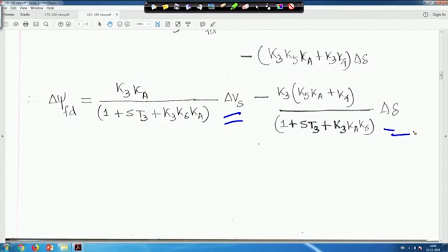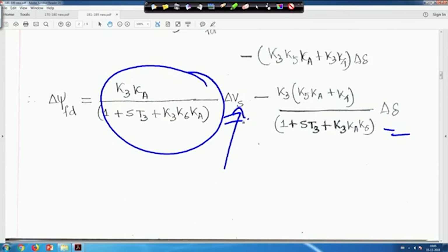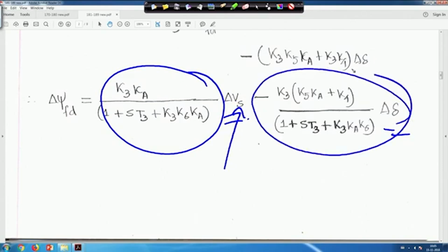So now this term has come into this equation because of the power system stabilizer delta Vs, right. Earlier, if it is not there, previously this term was there. But in that case you just neglect TR and do not consider delta Vs, then you will see this term is there. But due to delta Vs, this term has been introduced, right. So that means we have to see that it is providing damping. That is why this term is due to the output signal from the stabilizer, delta Vs, right.